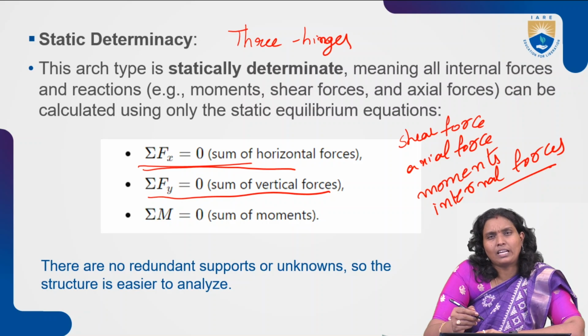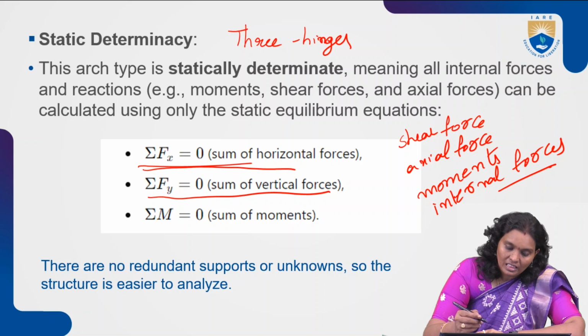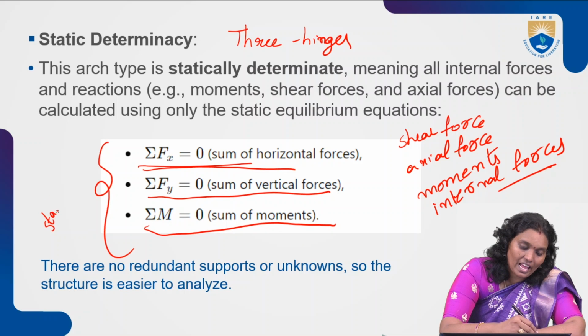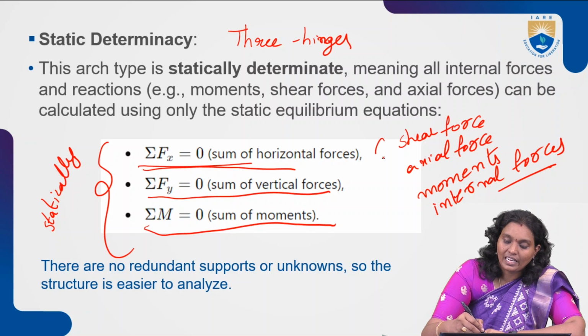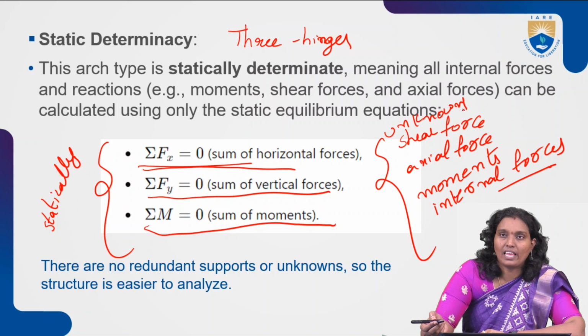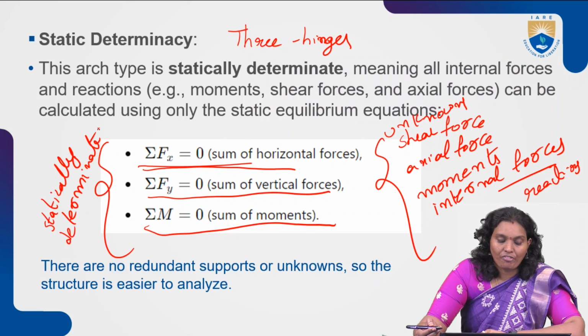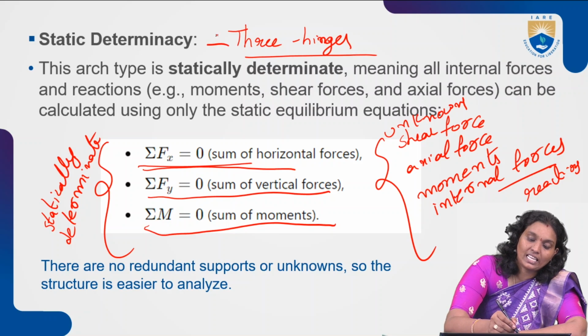We may have a variety of loads involved in that particular three-hinged arch. Even so, the sum of all moments should be 0. These static equilibrium conditions are enough for analyzing the three-hinged arch. Using these three equations is enough for getting these unknowns, reactions and also internal reactions. This statically determinate structure is enough. Such a type of arch, this three-hinged arch, belongs to statically determinate structures.